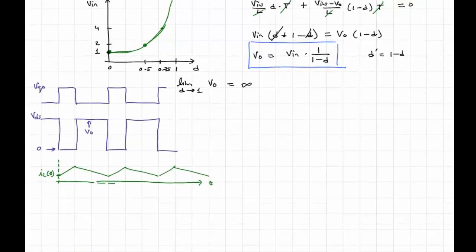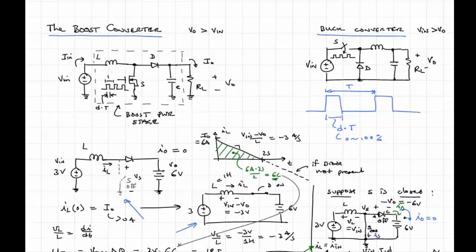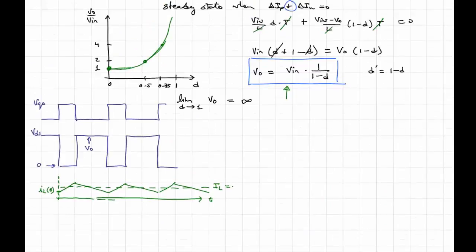So it turns out that the relationship here for the output voltage as a function of the input voltage, at least theoretically, does not depend on the actual average current that is flowing through the inductor. This average current here, this is IL, capital IL. This, remember, is the current flowing in from our converter. So it's this here, IN is IL. They're in series. So this average input current, or average inductor current, is the average input current.